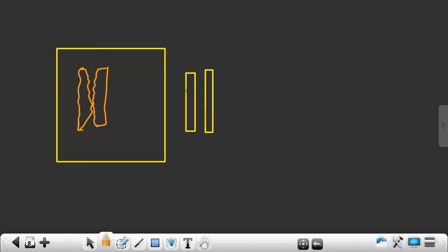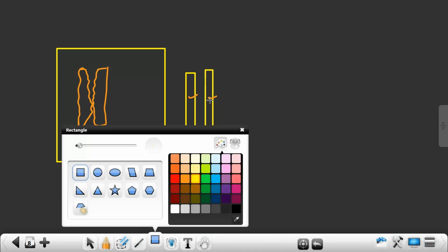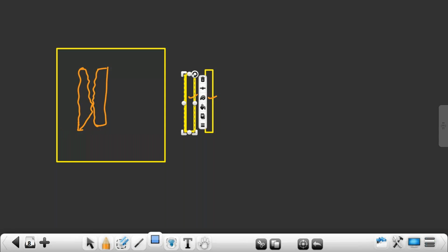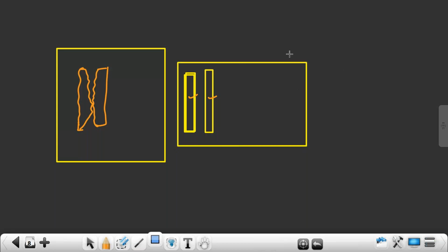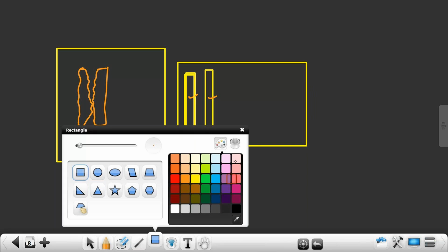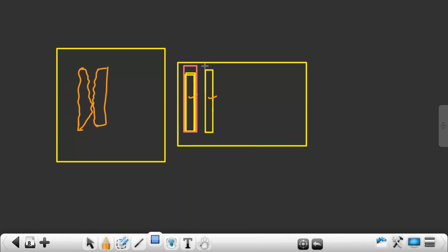So this is the metal layer which has to be fabricated according to our requirement, but the foundry cannot fabricate it like this. See how to form this metal layer. My foundry cannot form the metal layer only in this region. My foundry will fabricate the metal layer from here to here. The remaining regions it will remove through what? Acid. This region they will cover through a mask, this they will cover through a mask, and this region also through a mask. The entire region they will treat with acid.